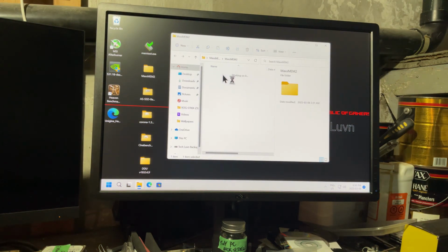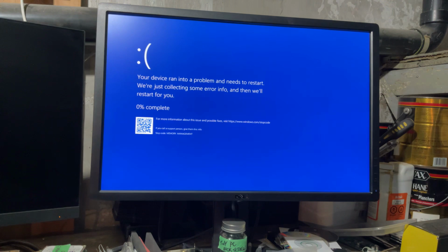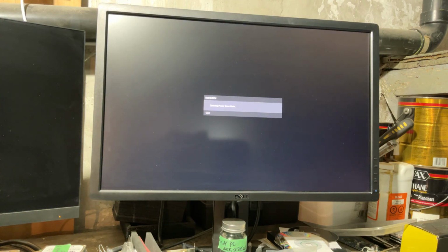So we got a program called, it's not stable. That memory clock is not stable at the 1.35 volts we have running in the memory. And that could just be a matter of loosening the timings.